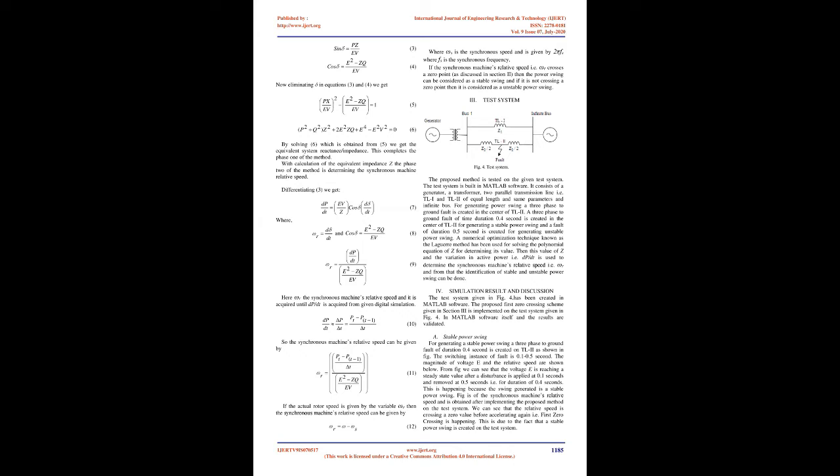Power swing and first zero crossing. There exists a power balance between the consumed and generated active and reactive powers in the power system network under balanced steady-state condition. But when a large disturbance occurs, e.g. faults, line switching, disconnection of generators, and the loss of large block of loads, it results in sudden change of electrical power consumption. As the mechanical input to the generator is constant, the disturbance triggers the machine rotor angle to oscillate and thus results in electrical power swing.